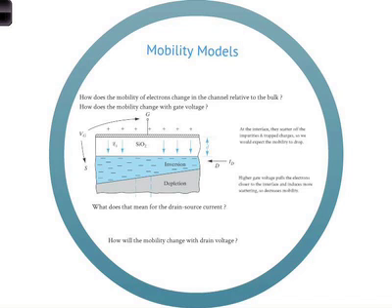Okay. So the electric field from the drain to the source, which is in the direction of the propagation of the electrons, will increase. Okay? It will increase, which means that we have a situation which looks like that. Like this, right? The same direction and so on. So increase this field, this will saturate. The mobility will, at some point, saturate, and this is the so-called ballistic transport. In fact, most of the transistors today actually operate in this kind of a regime.